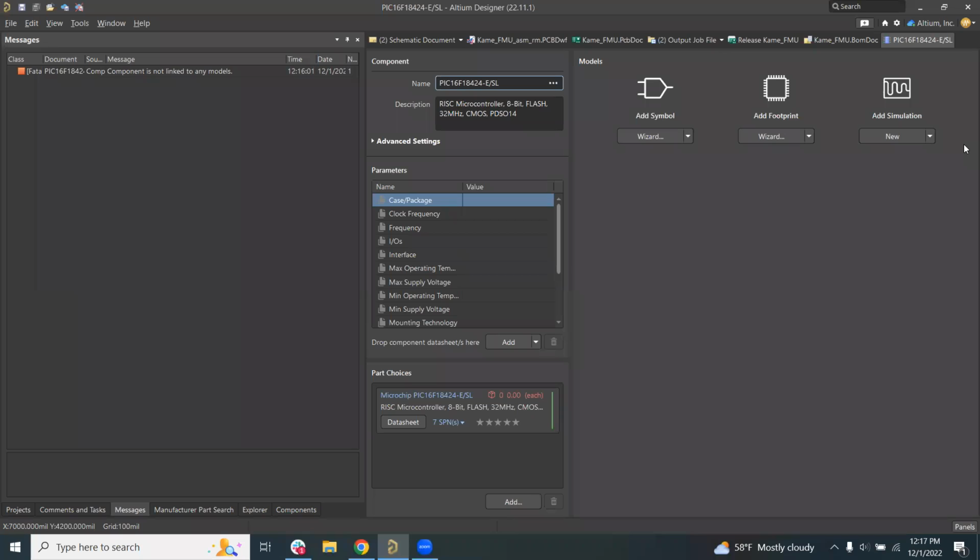Can we save our cloud library to our local server? That you would use the item card. We actually don't go the other direction. You'll have to download those from Explorer or through the components panel. We don't have a batch way of getting those from Altium 365 to your local server. If you're trying to go from your local server, however, into the cloud, we have the item manager that can help you with that. But as far as going the other way, it's pretty much a one-by-one selection of download.